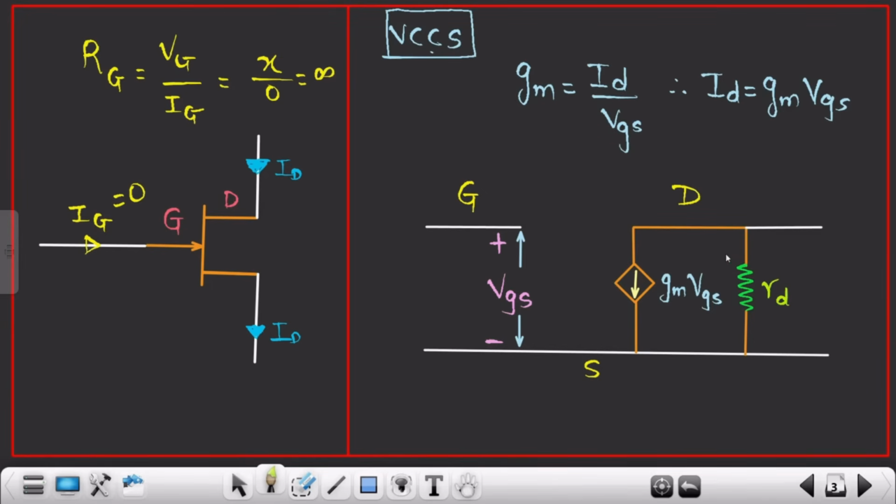But just remember, whenever you represent a current source, although I had explained that in the BJT course as well, the moment you draw this particular symbol, you have to draw one resistor as well, indicating the internal impedance of this current source. This is a concept related to network theory. Don't worry about this part, but as of now just remember this is RD. This is the internal impedance of a current source. This is also known as dynamic resistance when we are dealing with transistors.